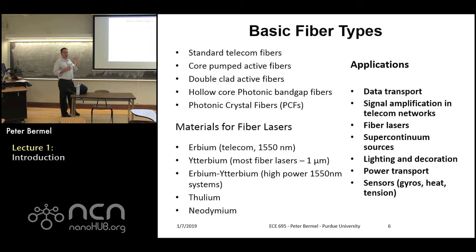The concept is when you send light down this really long cable across the Pacific, say, that's really thousands of kilometers. So in order to keep the signal at a strong enough intensity so you can actually detect it, you have to have amplification. And so that often introduces things like erbium-doped fiber amplifiers that take in the signal and then amplify it using re-emission of erbium at a specific wavelength, which is 1550 nanometers.